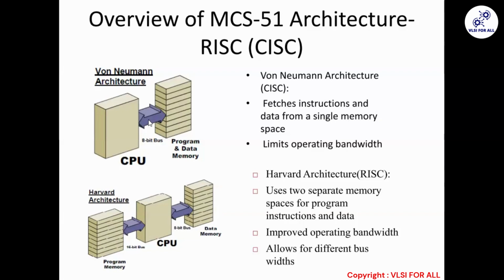Whereas in von Neumann, what is happening? A single 8-bit bus is there. At first, it has to take the program. That program will be decoded. When that program says that from a particular location we need data, again it will go and fetch the data. So that is again the limitation, as well as this bandwidth, which is of 8-bit. Instructions are also of 8-bit, and data is also of 8-bit.